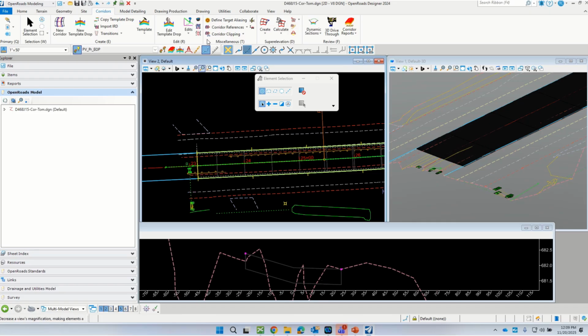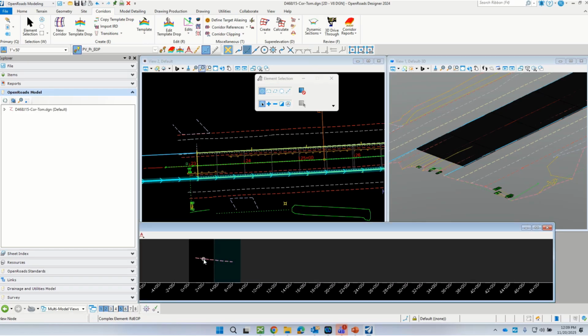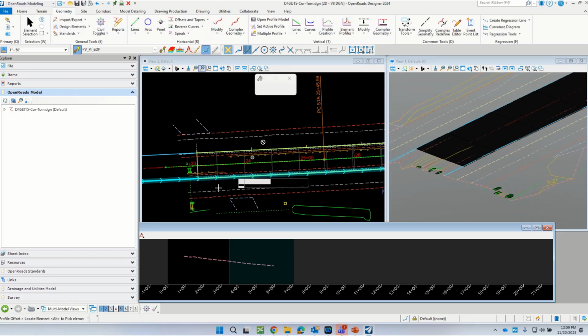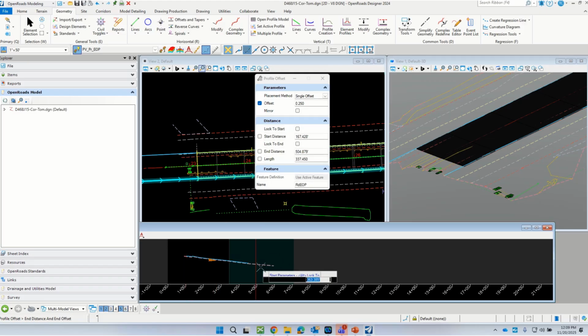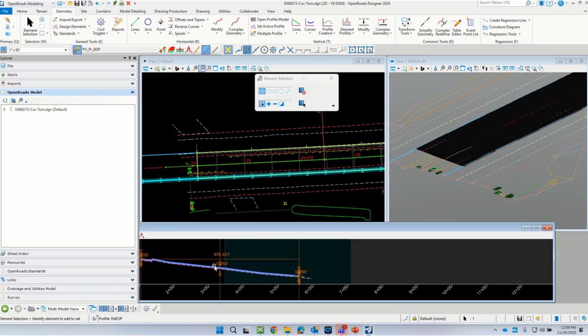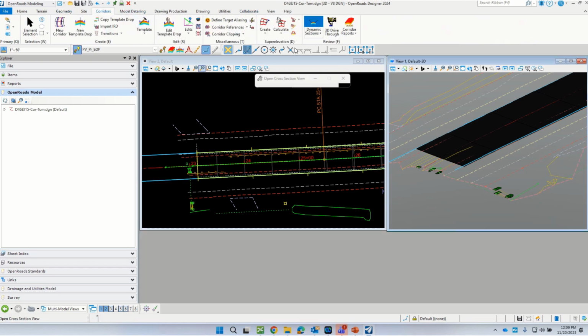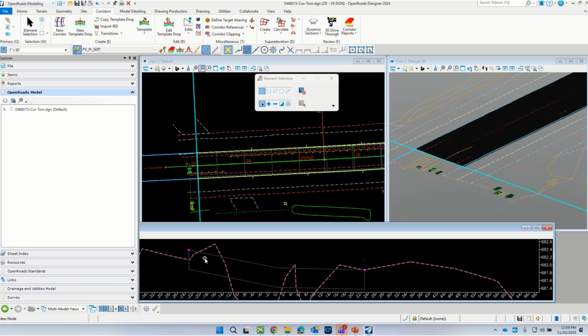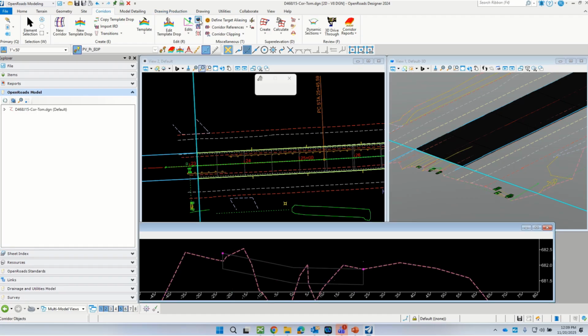But now we should be able to do the same thing with the other side real quick. We can go ahead and create an additional point control, but really we're just going to change the active profile over here, again, from that existing to, if I go to geometry, offset, select the existing, create that profile that's parallel to the existing, and then hopefully right when I make that the active profile, and I look at the cross section, I could have just kept that up in a separate view. Oh, I can see there that it didn't grab it either. I'm not sure what's up with that.